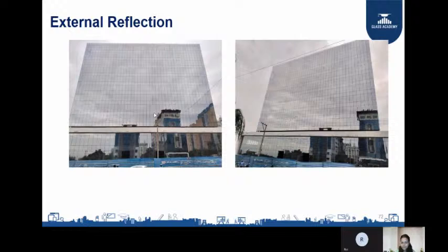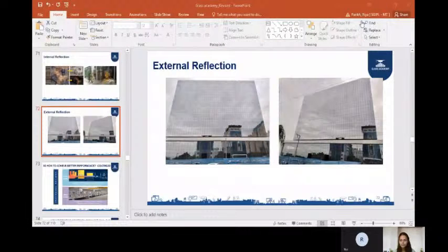So now you can see I have taken one example where solar incident energy is 630 watt, and temperature difference I have taken 15 degree, right? SHGC of the glass I have taken 0.3 and U value of the glass I have taken 3. Now DHG is direct heat gain and IHG is indirect heat gain. To calculate DHG, I will multiply solar factor with solar incident energy, 0.3 into 630, which will give me 189. And U value of the glass, I will multiply with the temperature difference, 3 into 15, 45, right?